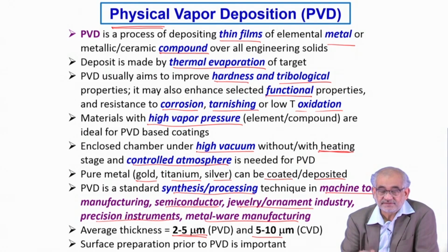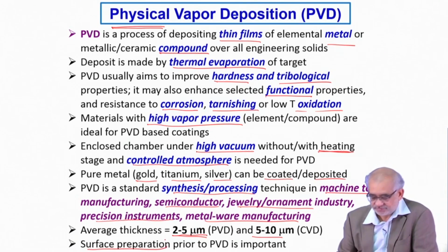But we need to clean the surface well, remove not only any kind of oil or grease, but also any presence of thin oxide layer, because that's going to then not allow good adherence of the deposited film onto the substrate. So surface preparation is very important.